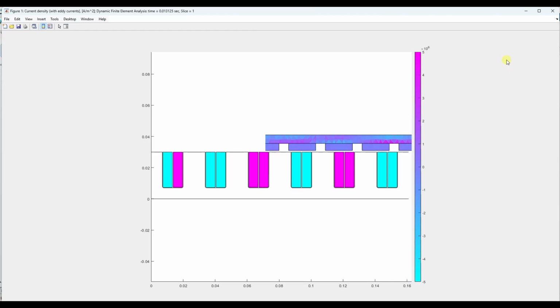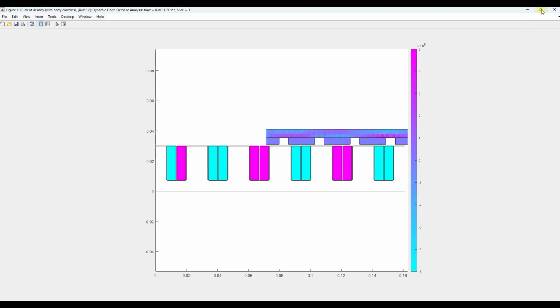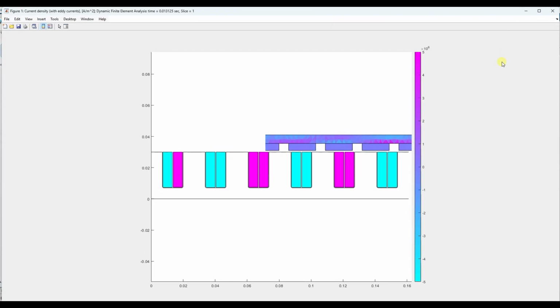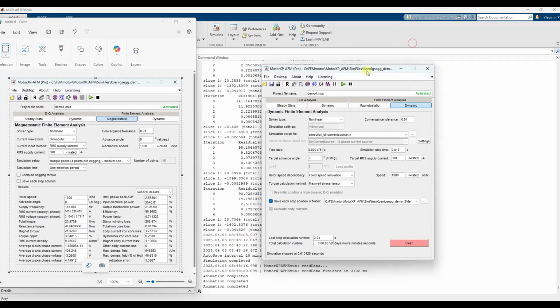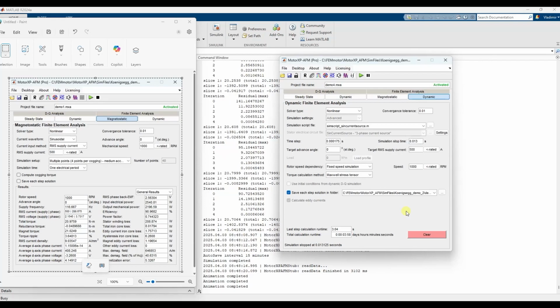Okay, do you have any questions? Hello? Sorry, I was listening muted, but yeah, I think nothing in particular right now. It's actually very interesting, seeing the way we are launching this through the dynamic, with the scripts that you already have available through the MATLAB version, where you can input current with a PWM pattern, right? Yes. So it's even more powerful, because in the end, apart from computational time, nothing is stopping us from simulating even the effects of PWM on the eddy current losses in the windings and the magnets. Sure. Yeah. Including in the stator core, actually. That is the part that is impressing me a bit, that you are putting a feature available to compute the eddy currents in the laminations itself.